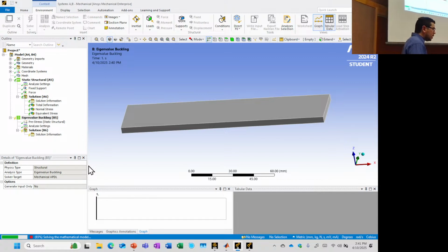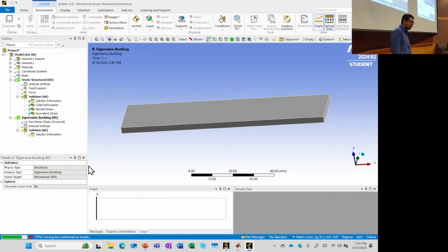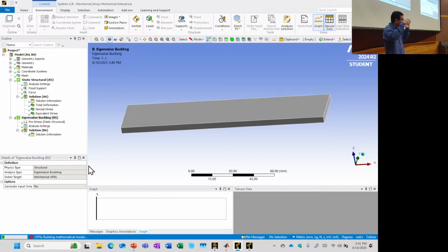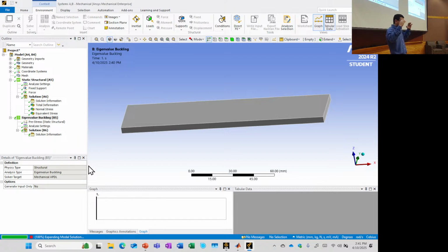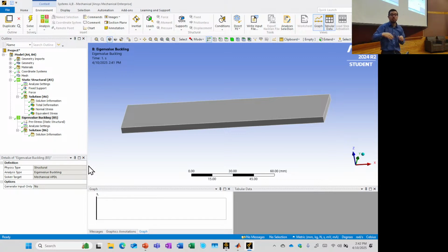What's interesting with this eigenvalue buckling analysis, and maybe when you take vibrations you'll talk a little bit more about this, is that you'll have modes that this eigenvalue analysis illuminates. On a kind of impressionist perspective, what we're saying is that as you compress, there is one mode where this top piece, or side piece if you turn it this way, springs out this way, and that would be one mode. When you're pushing down, you could also have it push out sideways. That would be another mode.